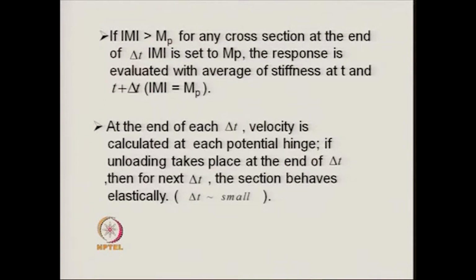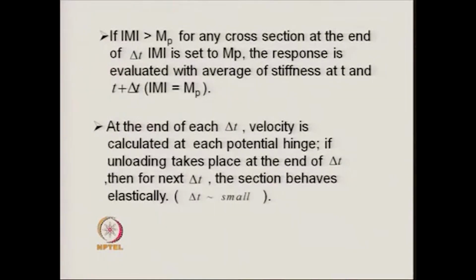then at the end of the delta t, what we do is that we do not modify the calculation the way we had done for a two-story frame or a single-story frame, where when the system passes from the elastic state to the plastic state, then we find out the point at which the plastification takes place, and therefore apportion the loading, incremental loading, into two parts.